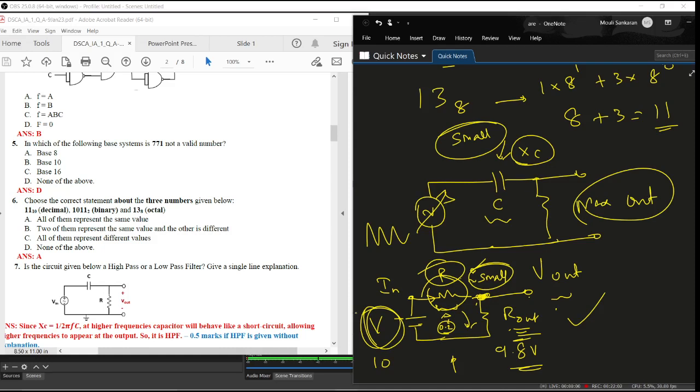So when I increase the frequency, suppose, what will be the reactance? Now reactance across the capacitor, I have given you the equation there, omega C, which is nothing but 1 by 2 pi f into C. So the frequency component is below. So if I increase the frequency, I am going to get this XC value going down.